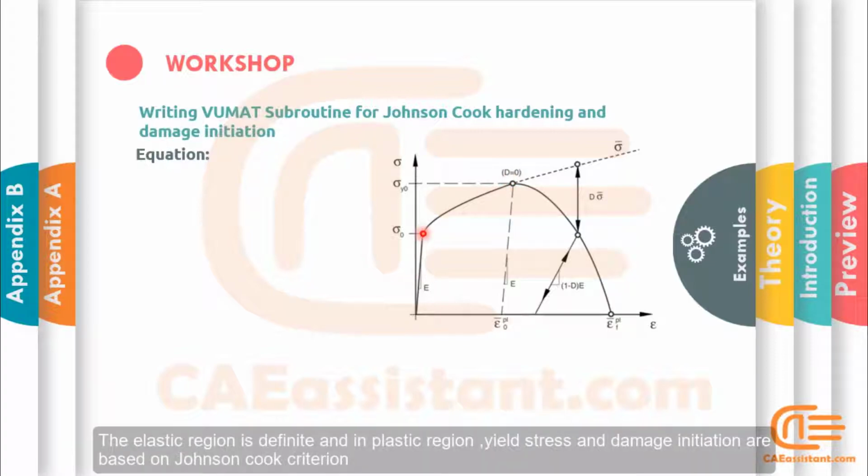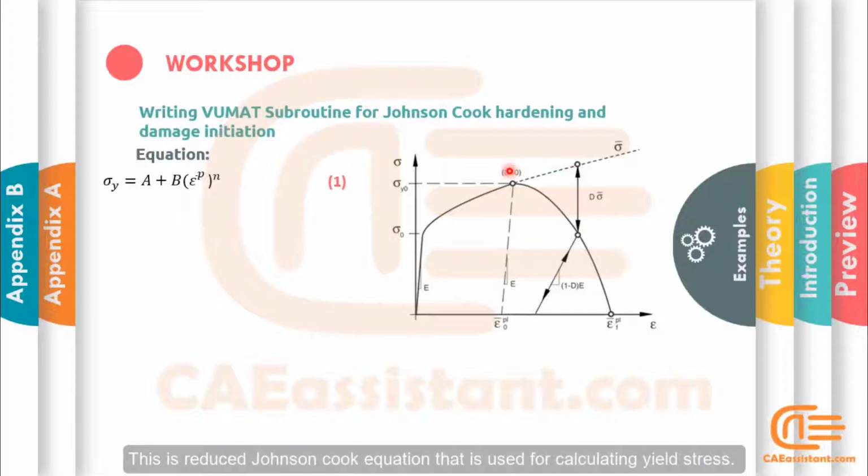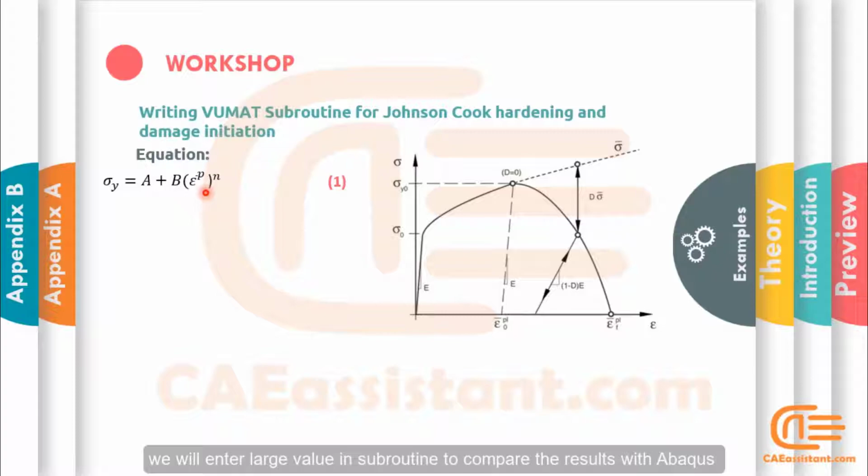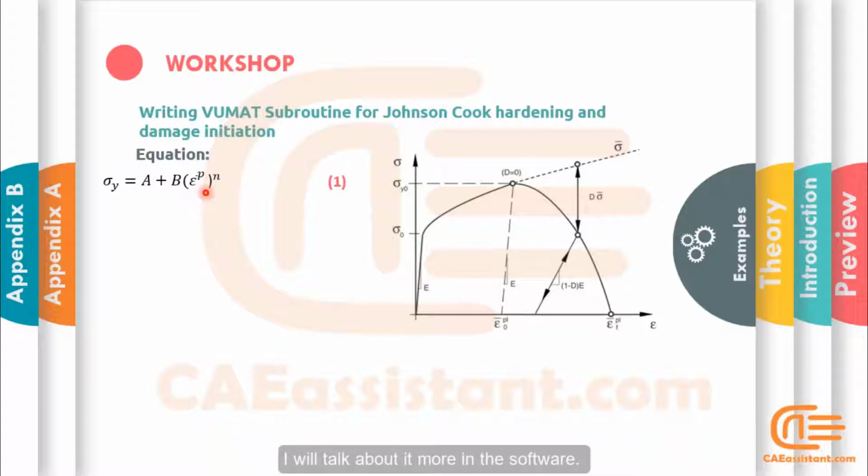The elastic region is definite, and in plastic region, yield stress and damage initiation are based on Johnson-Cook criterion. This is reduced Johnson-Cook equation that is used for calculating yield stress. It has a thermal coefficient, and because Abaqus considers a big value for transition temperature, we will enter a large value in the subroutine to compare the results with Abaqus. I will talk about it more in the software.